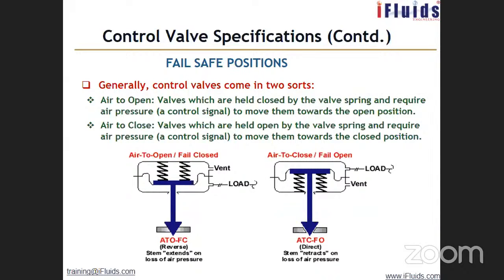So that is why, in the input data we give to the instrument engineers, if the liquid is closer to its boiling point, you have to be very careful about the pressure drop across the valve. Also, if there is a two-phase flow at the inlet, you have to indicate that, and then they have to design a proper control valve to handle the two-phase flow. If flashing happens, downstream of the valve will have two-phase flow.